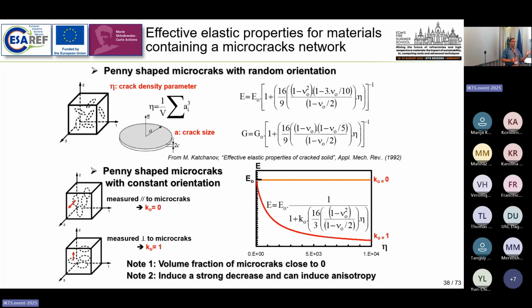So this is absolutely crucial in many cases for thermomechanics, for many applications in which refractories are confronted with huge thermal shock. You need to put microcracks in your design in a very tailored way, and this is a key point to obtain the pertinent thermomechanical property you would like to sustain the conditions of application. And of course, a lot of work has already been done far away, typically 50 or 60 years ago.